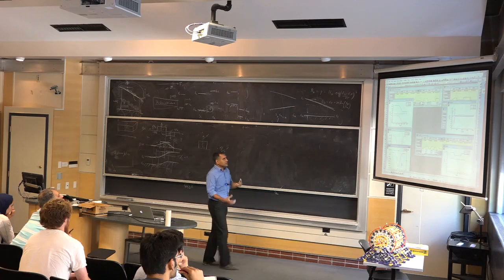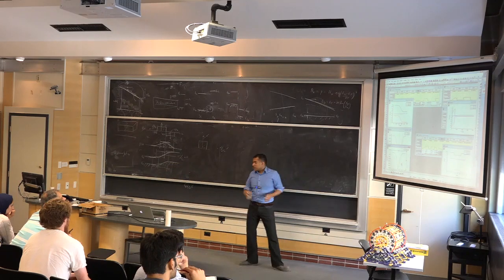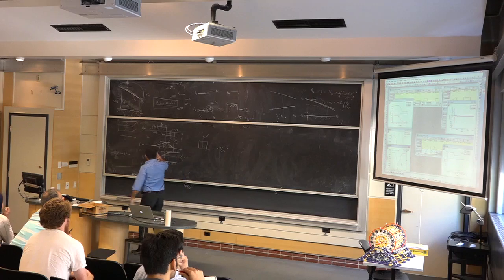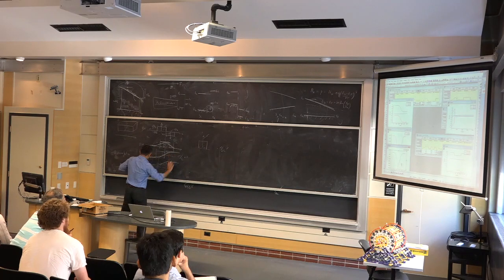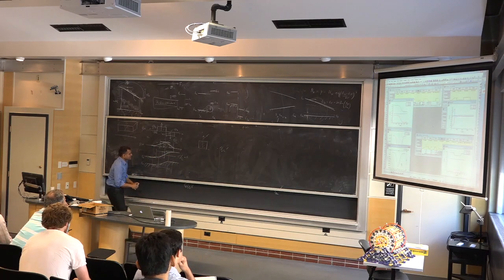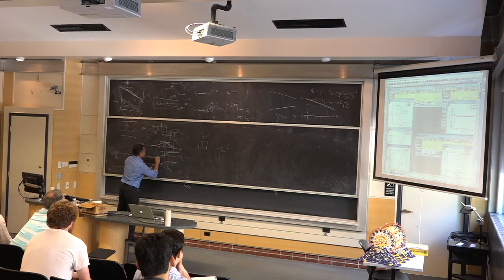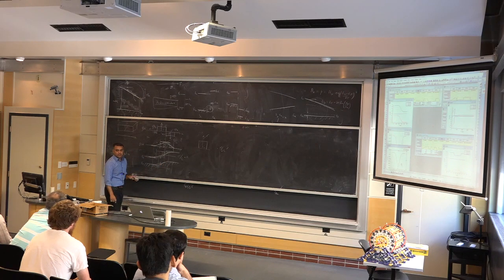What it does is it solves the Poisson equation, but at the same time, if I don't have the same semiconductor material all throughout, if I have things that happen inside this material, for example, I put a little quantum well, which is a narrow bandgap material. Let's say I can do that. In fact, that's a very useful device. It's an LED, light emitting diode structure.